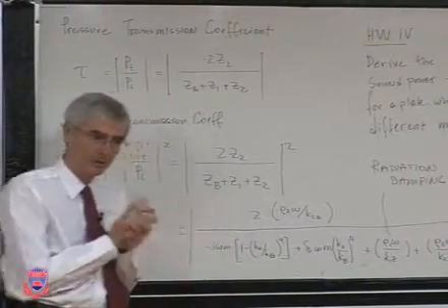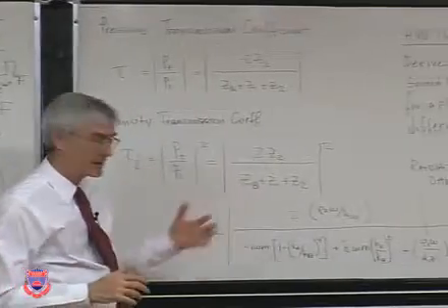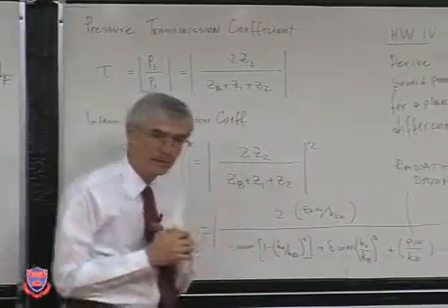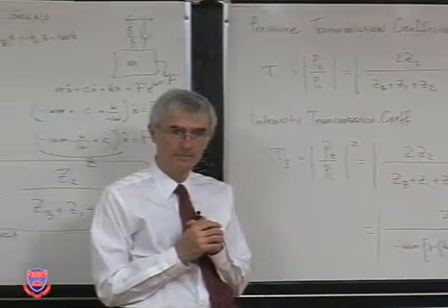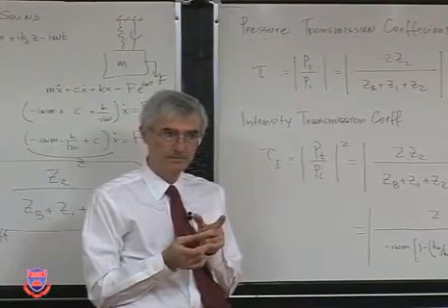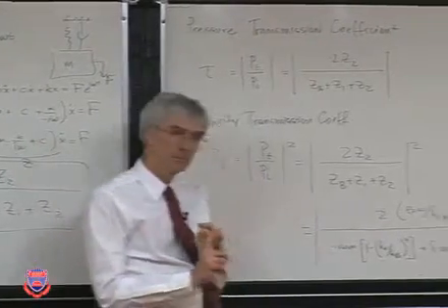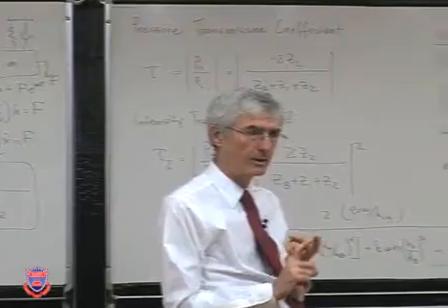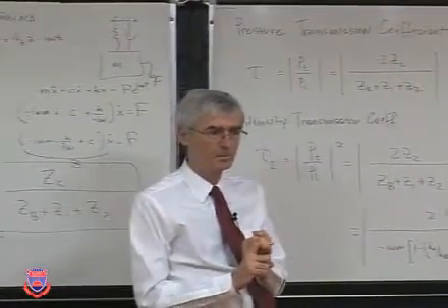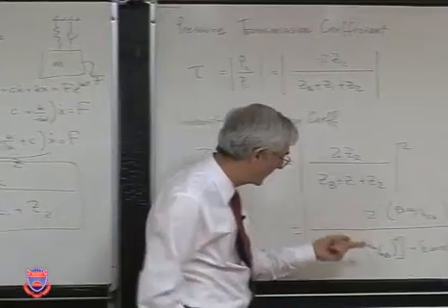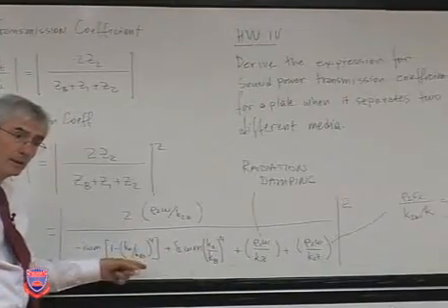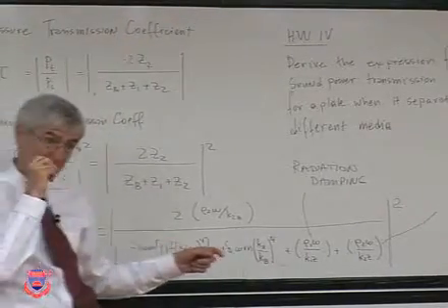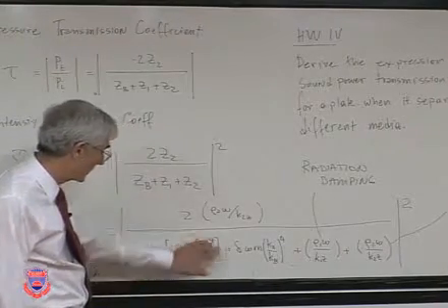It has more stories to tell us. Okay? If instead of being a plate, this were a membrane, what would be different? There will be no damping. Membranes can have damping in them, but go ahead. What else? No stiffness. Okay, so what would happen? Stiffness, where does the stiffness come in? The stiffness comes in through the bending, right? Bending vibration or bending modulus, so this would be 0.